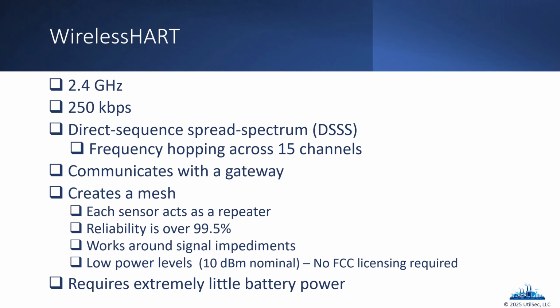I did want to also talk about wireless HART. This is one of the more OT wireless protocols that I like. The idea is that we use it from a wireless perspective to create a mesh for sensors to be able to report information back to the rest of the OT network, right? To where they're trying to get the sensor data, like to our PLCs.